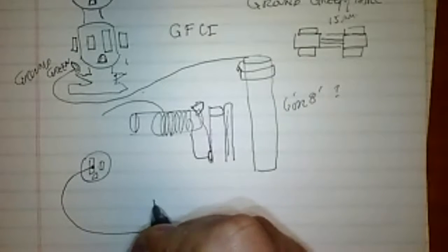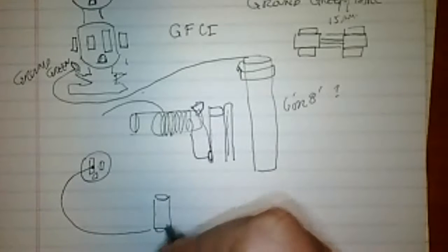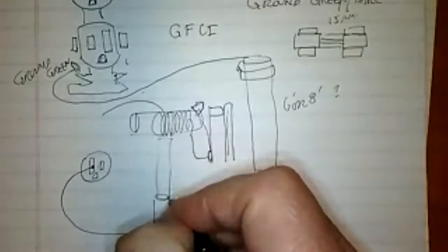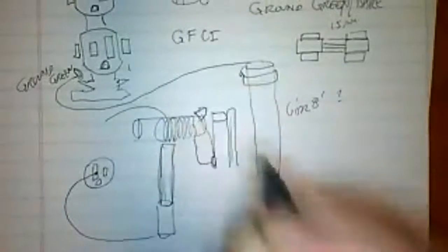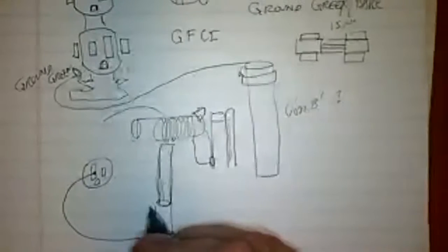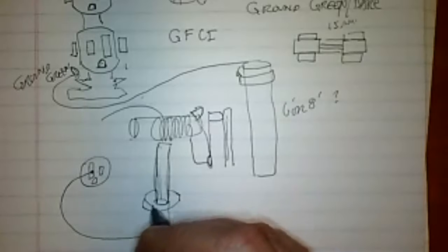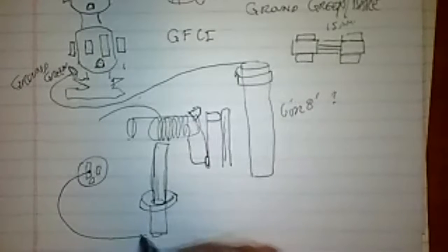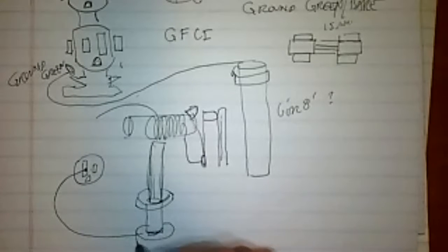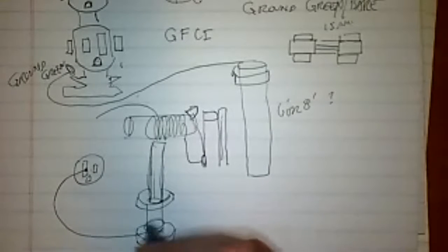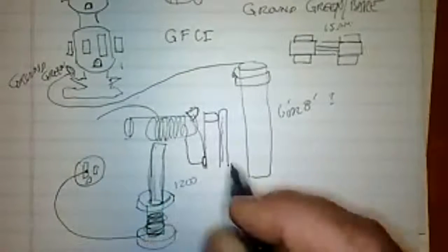and then I took a little piece of PVC and put it around a steel rod, like a horseshoe stake, basically. Okay, so this is a steel rod, so that I'm making an electromagnet once I wrap the coils around it. And then I put a little Teflon cylinder around it like this, so it made it like a spool. And I put another Teflon spool around this end, so I had nice, neat ends. And then I wrapped it around this about 1,200 times. I did it with a lathe.